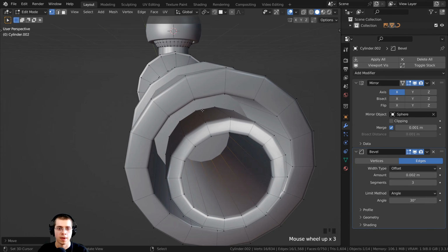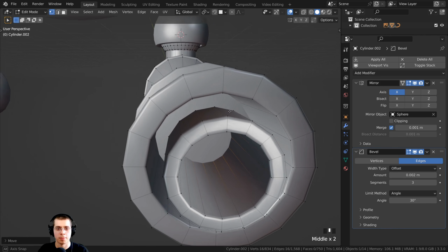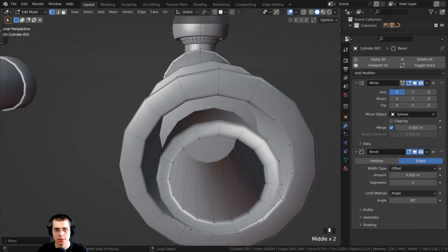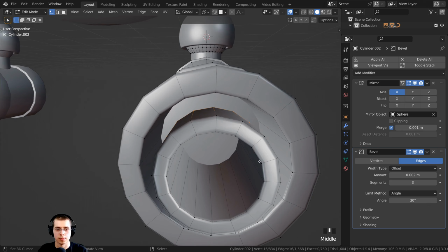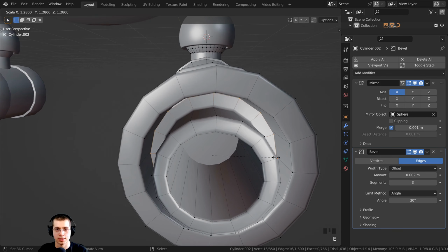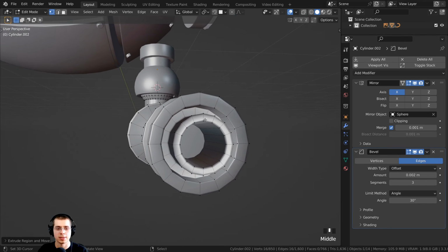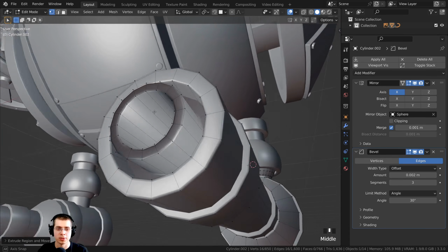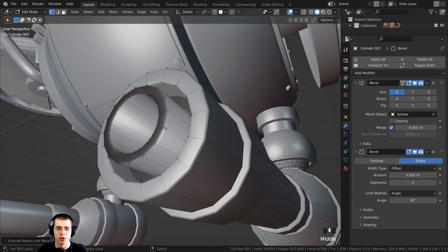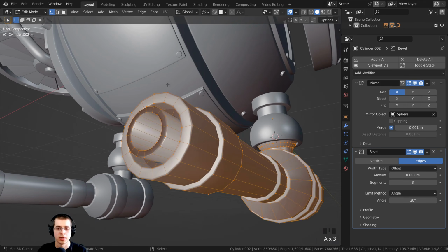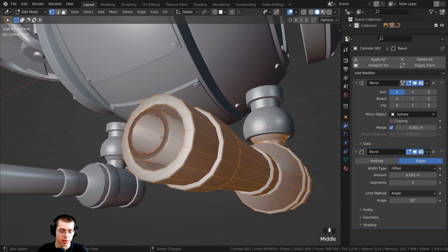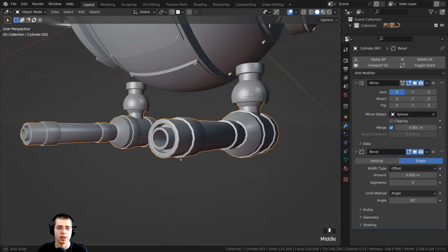and just stick it in there. And then also I want this piece to be extruded up and out. So hold down the Alt key, select that loop right there. I can press E to extrude and then S to scale and scale that up and place that there. All right, so now we have that back face in there. And then we also need to recalculate the normals. I can tell because the shading is a little bit weird. This is darker, whereas this is lighter. So press the A key to select everything, and I can press Shift N to recalculate the normals.